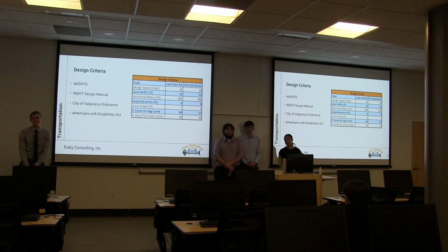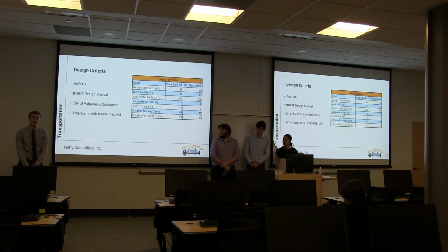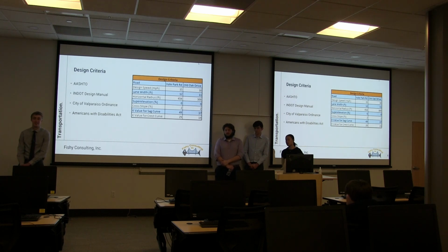Since you're answering questions, Hunter, I have one question, and that's for your wet pond with the floating treatment wetlands. How are you going to maintain water in there? Is the water table that high, or are you going to need an impermeable barrier underneath the wet pond? I think the water table's low, so we're going to have to implement an impermeable barrier to keep the 3 to 8 feet water level within the pond. Okay. And one other question: are you designing the treatment wetland and the plant selection and all that? Oh yeah, I'm going to be designing that. Okay. Any other questions?